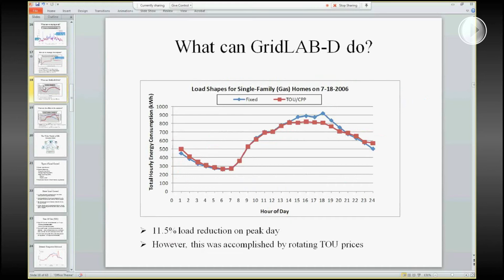This was some work we did with some partners from NRECA. They wanted to understand what their max capacity was for reducing load. So again, this was time of use prices, actually rotating critical peak prices, going through and creating 4 bins of customers and rotating them through so that they got the right mixture, so we could get a perfectly flattened load.